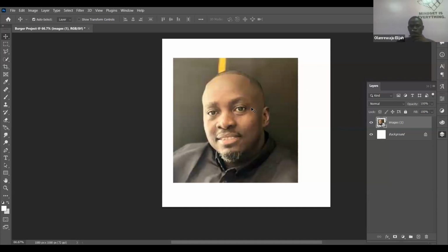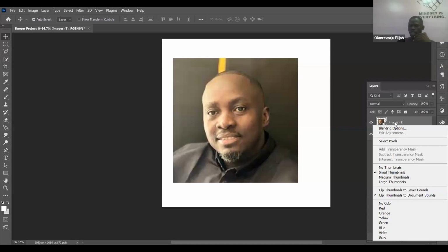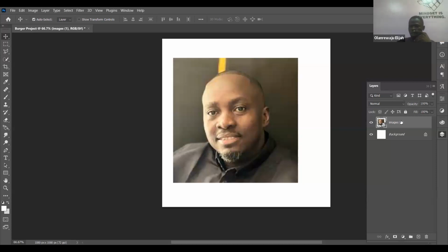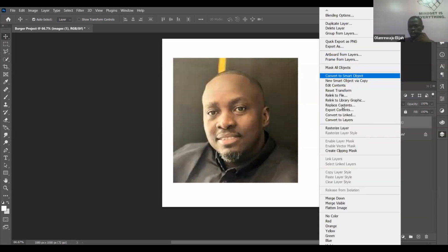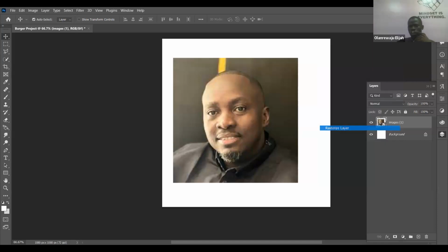Right. So now this is the person that you want to crop. But you know that this guy is already an object, a smart object. Before you can crop it and remove the background, you must convert this smart object to an image, to rasterize it. This is not an image, it's an object. To convert it to an image, you click on that image and rasterize it. Right? Can you see now that the smart object thumbnail is gone?